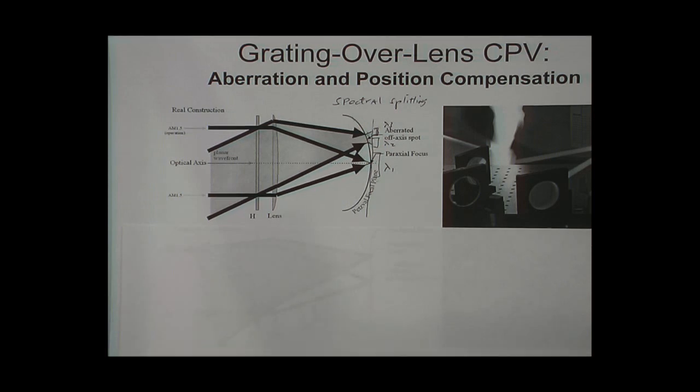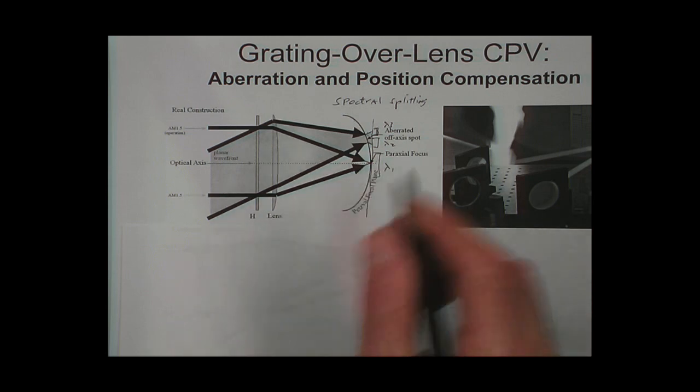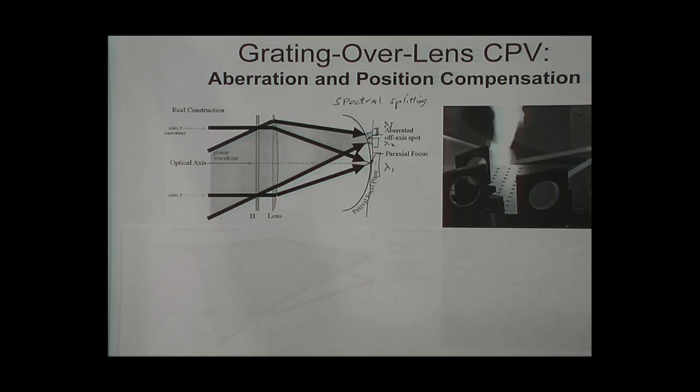It ranges from about 350 nm out to about 2 microns, where most of the power density in this solar illumination spectrum is. If you try to do that with a single bandgap cell, you can only capture about 33% efficiency due to thermal considerations.